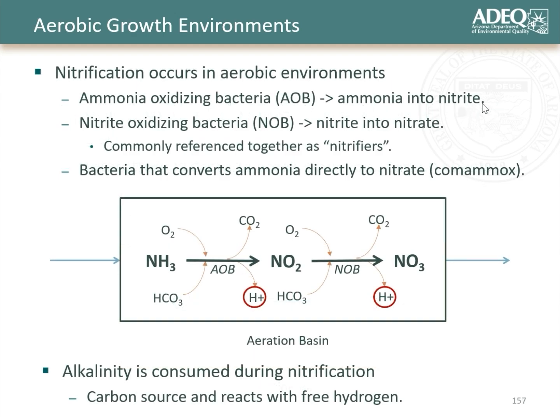Similarly, nitrification is also an aerobic process, which is a little bit more complex because historically and primarily, this is a two-step process in which a different type of organism than the heterotrophic bacteria will take ammonia. You give them ammonia, give them oxygen, and these bacteria, specifically the first step, which are called ammonia oxidizing bacteria, will take ammonia and convert that to nitrites. The nitrite that's produced from those ammonia oxidizing bacteria will then be fed to nitrite oxidizing bacteria that, under aerobic conditions, will take the nitrite and convert that to nitrates.